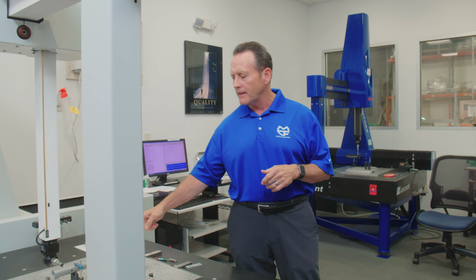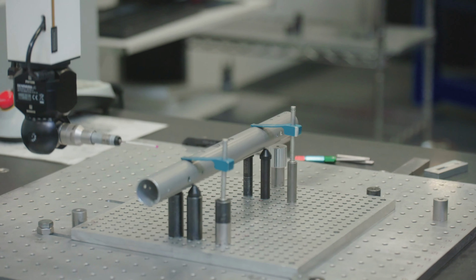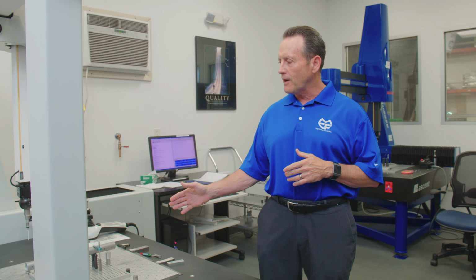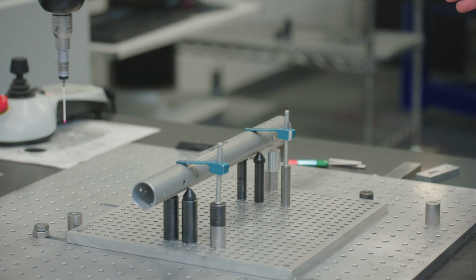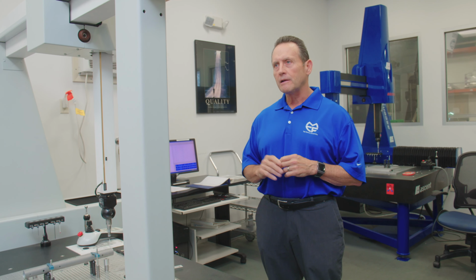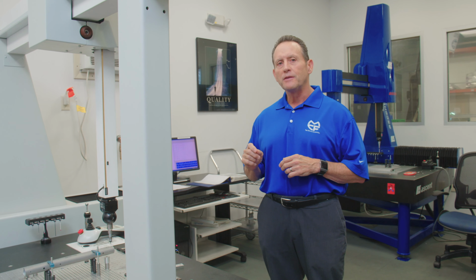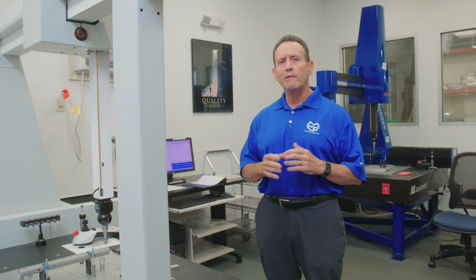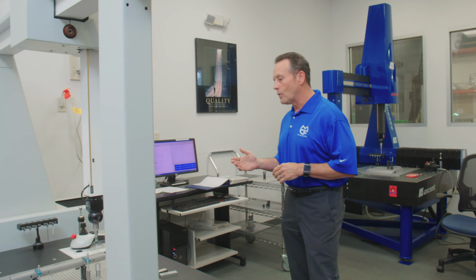Once the product is brought in, as you can see, it's identified with a serial number. Like we talked about earlier in the process, everything going through our manufacturing facility is identified with a serial number, and that is entered into the CMM program. Essentially, the probe goes around the part, touching points, collecting these points to create geometry. From that geometry, they create relationships. From those relationships, they start to develop the relationship between the part and the drawing requirements, including the tolerancing that's built into the program.